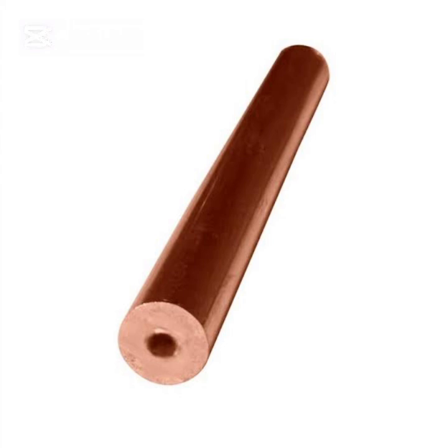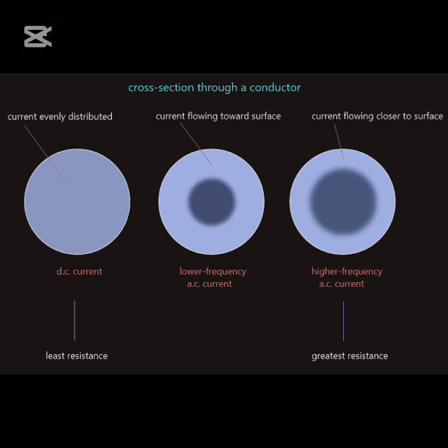Since the inner core carries minimal current due to the skin effect, it can be removed without major drawbacks. Lastly, reducing the AC current frequency, which increases skin depth and mitigates the skin effect. However, this approach is not always feasible for applications requiring high-frequency signals.